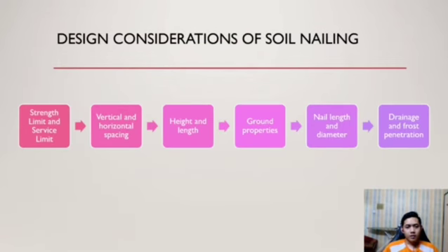And these are the design considerations of soil nailing, where in this process we identify the following factors: strength limit and service limit, vertical and horizontal spacing, height and length, the ground's properties, the nail length and diameter, and lastly the drainage and frost penetration.